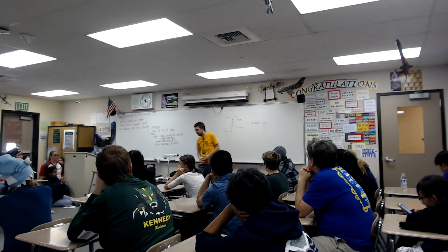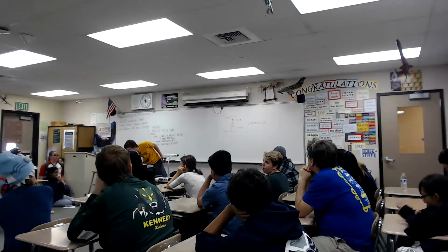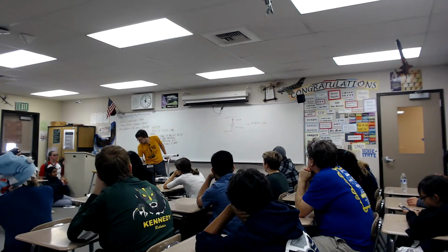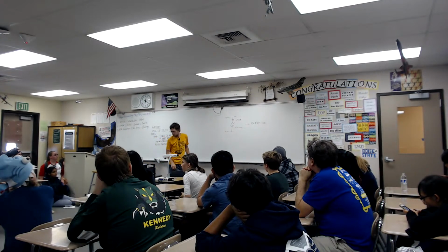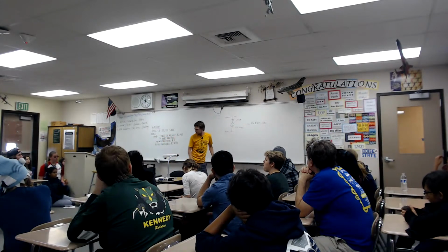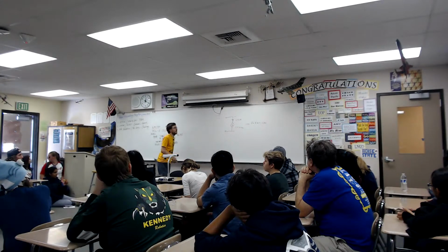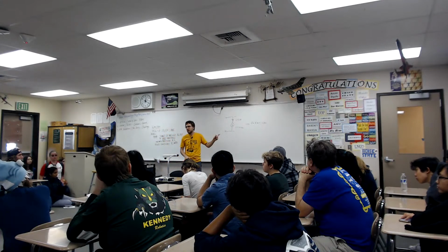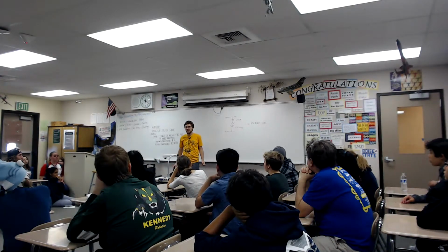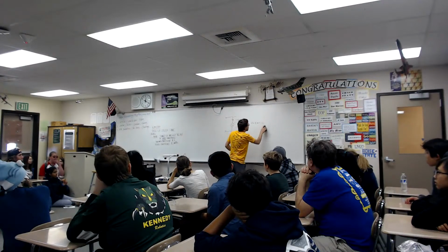Actually, hold on, let me make sure I got KV the correct direction. I think it should be divided by KV. Yep, sorry. The physics works out if you do KV or 1 over KV, but if we use the right conventions, it will match what's used in all the literature. So it's omega over KV.